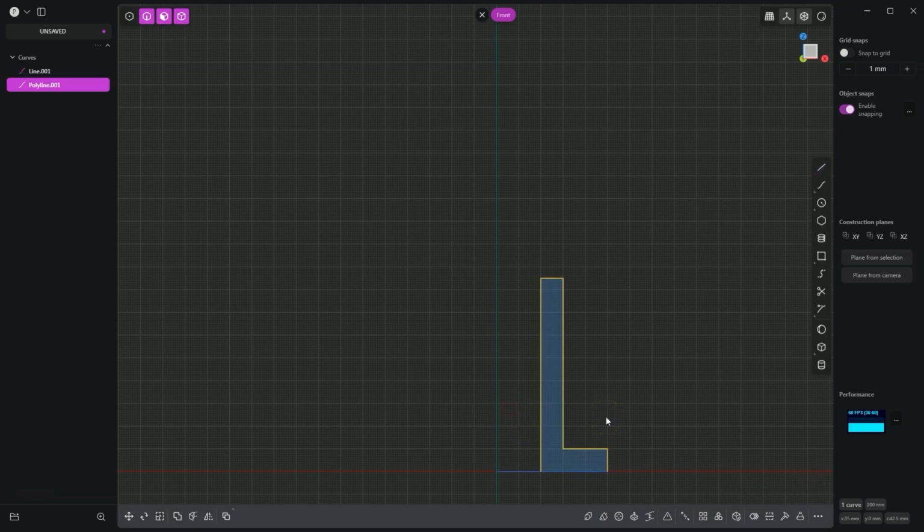In this way, we have created a sketch, based on which we will create a solid by rotating this sketch around a specified axis. Here we can also remove this segment of the line. Let's select the Trim command and click here, and this line has been removed. Right-click to cancel this command and close the view of this plane.